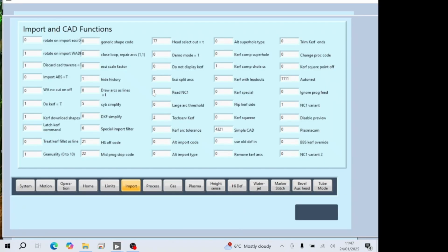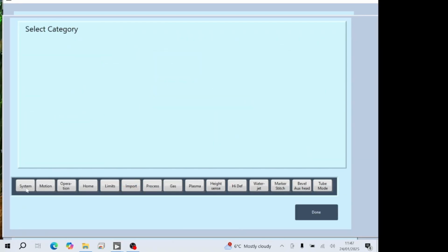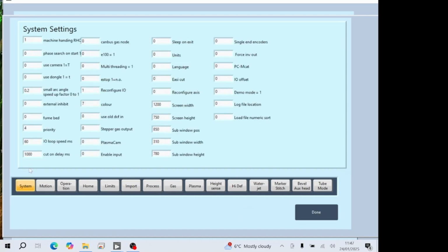This takes us onto our configuration screens, which gives us access to the functionality of the system and how it's set up. So we'd use this if we're setting the machine up as a gas machine or a plasma machine, or specifically for a duct cutting machine, where we'd always run from the same origin, auto load plates, and drive off the plate once we've finished cutting.